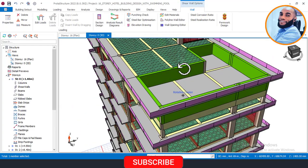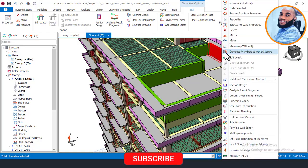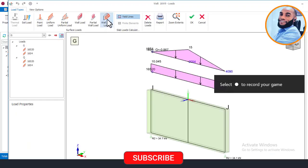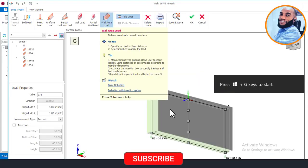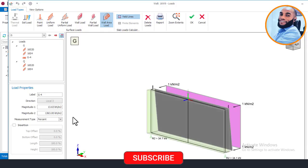Okay, so right now we have to also come here and add up for this other one. So we are almost done with adding the load here. I'll come again right now and click on edit load here. And then I'll click on this surface, this wall area load here, and I'll click on the wall here, and I'll come here and add my load, 13.63, and I'll come again here right now, 13.63.